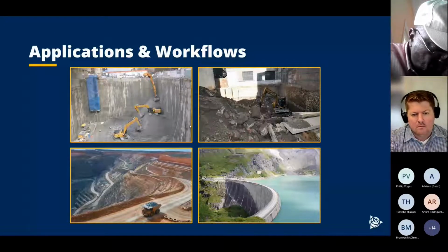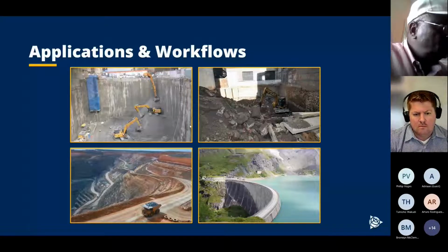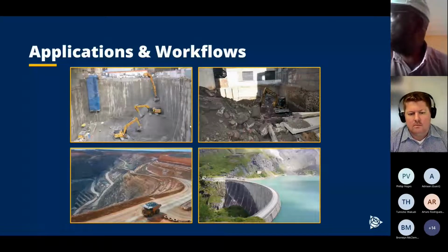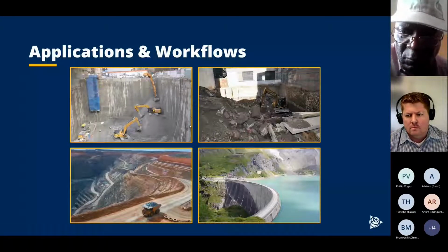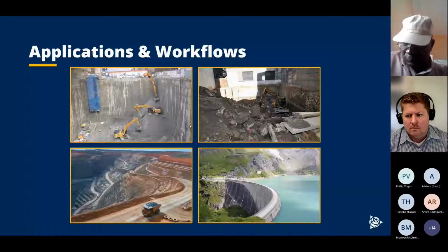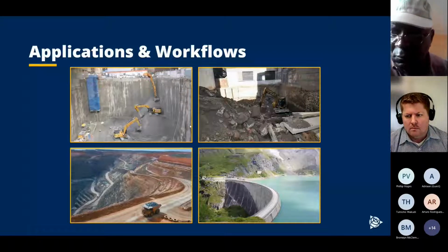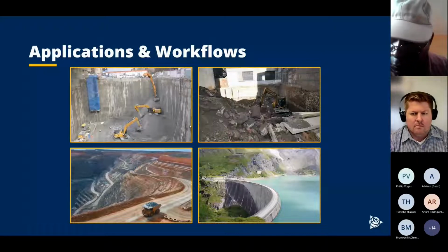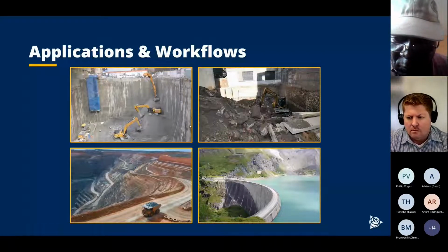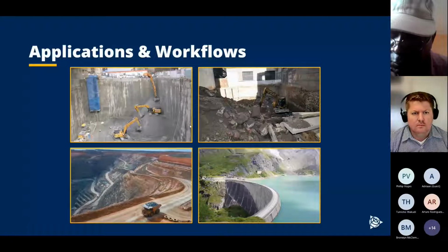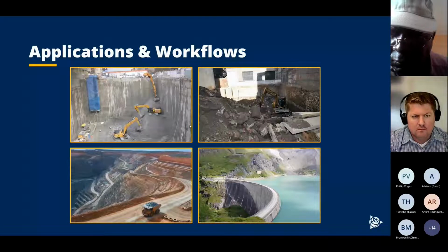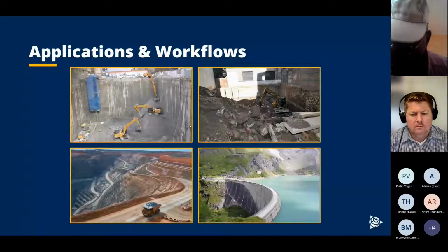Or for example, a smaller one on the top right side. This is something that typically happens in every little town. There is an old building that has been torn down, and now there is new construction going on in the gap that came up. But you still want to see whether your construction has any impact on the buildings around. So you maybe go there once a day or once a week and do your deformation observations on the buildings adjacent to the construction going on.